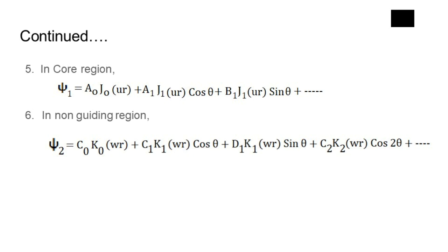Now, in the case of a dielectric core and dielectric cladding waveguide, the field solutions and their first derivatives must match continuously at the arbitrarily chosen points according to Goell's point matching method. So, after matching the fields and their derivatives at the chosen points, we obtain a matrix of a very high number of equations.